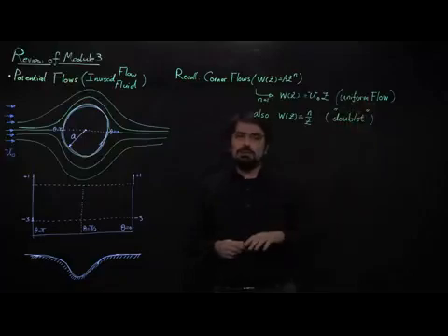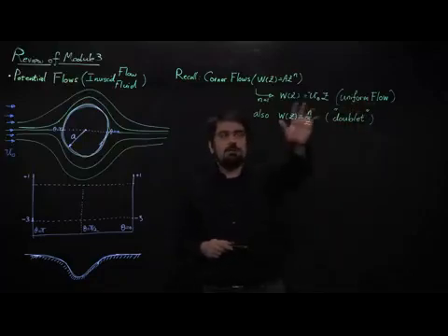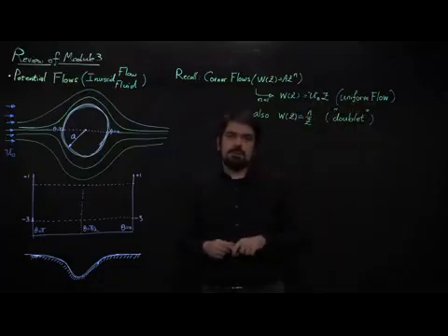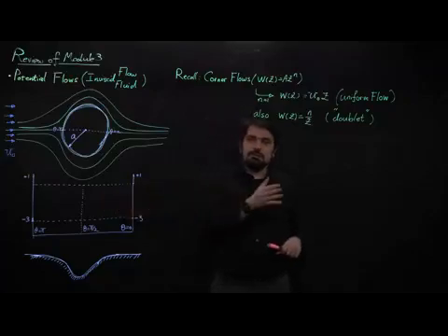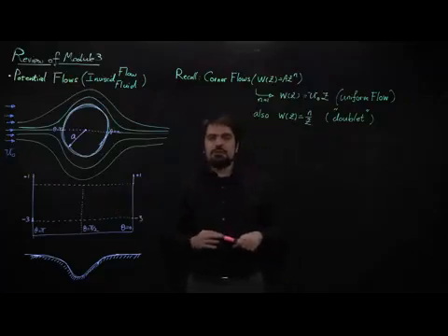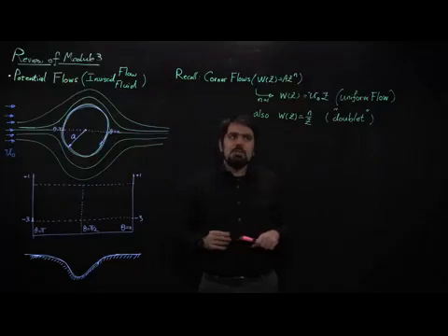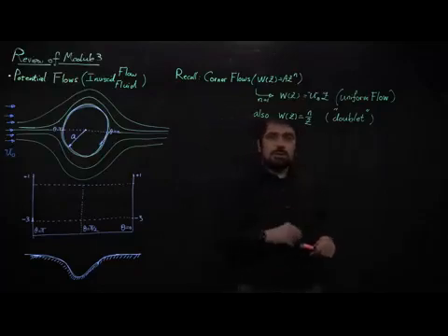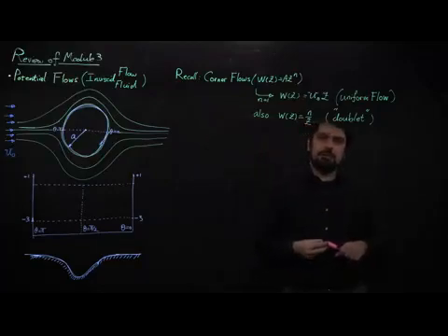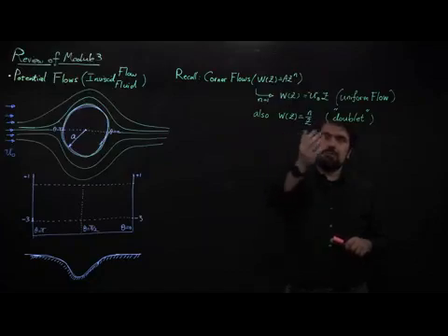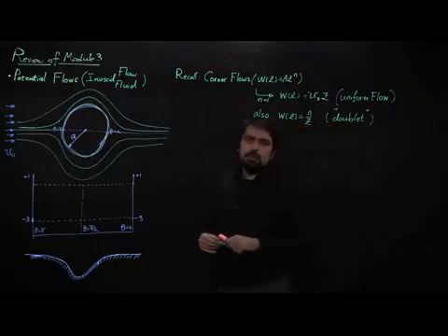It's a uniform flow. W(z) becomes U0 times z, and that's a uniform flow that everywhere in the domain has exactly the constant value U0. We also saw that we can construct some more complex shapes and geometries with our flows. For example, if you take the other analytical function, W(z) equal to a constant n divided by z, in the lectures we discussed that it will give you what we call a doublet.